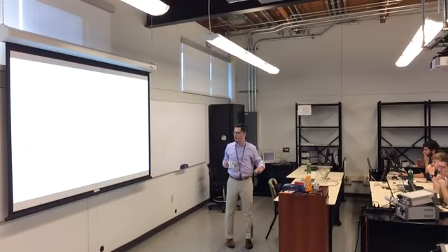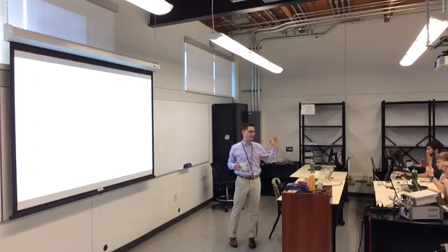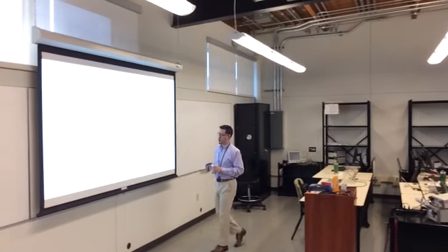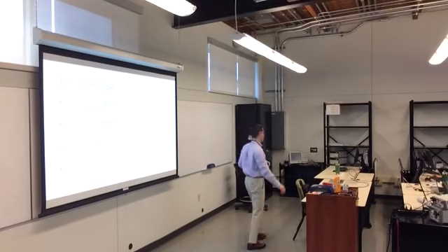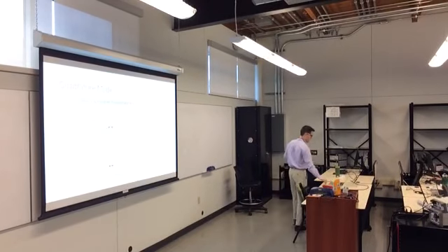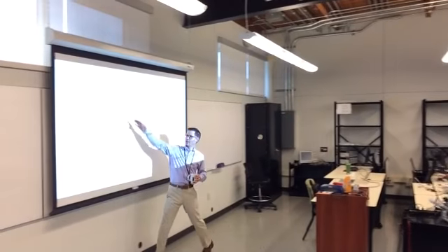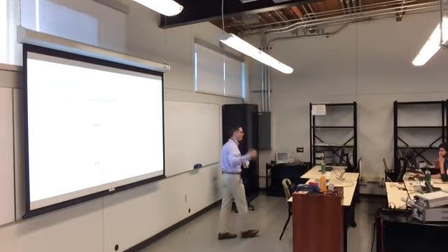So things that do wheel speed and spin, these are these square waves, and you want to know the time between the edges of the square waves, which implies how fast the thing is spinning. And you don't want to write software for this because it's annoying. You would rather just set up the quad encoder to do it for you. So in the quadrature mode, you've got two signals that are out of phase, and you want to measure the time between those edges.